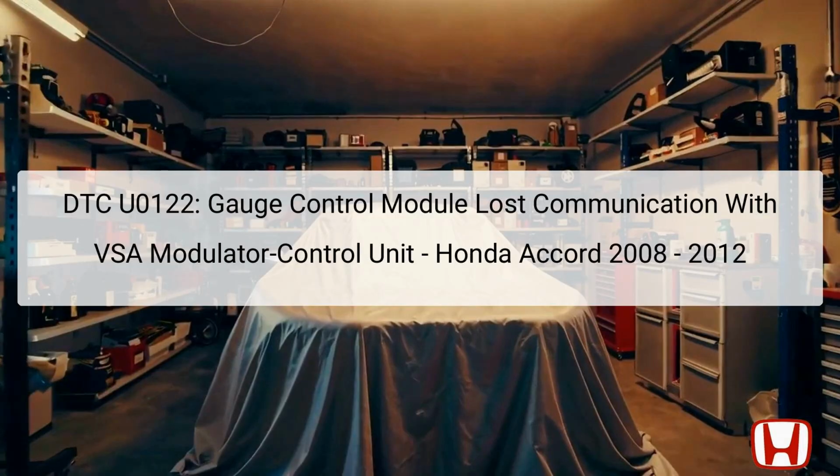DTC U0122 indicates a communication failure between the gauge control module and the Vehicle Stability Assist (VSA) Modulator-Control Unit. The VSA system is responsible for enhancing the stability of the vehicle during dynamic driving conditions by controlling brake force applied to individual wheels to prevent loss of traction. The gauge control module displays relevant information and warnings to the driver, such as speed, fuel level, and stability alerts.